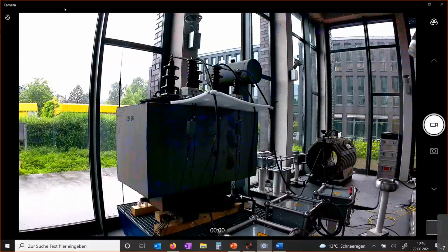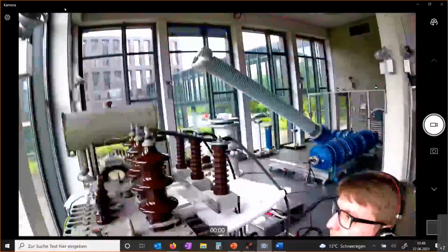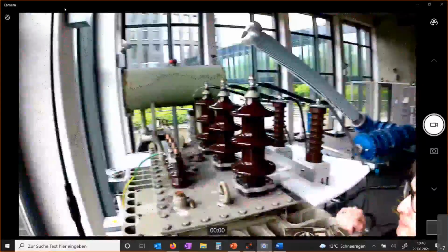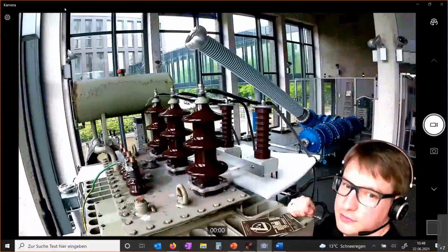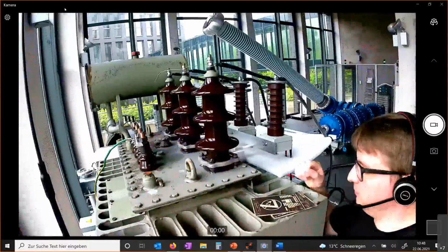Also, my colleague showed you how useful the spectrum analysis is. This is something mostly not available in most equipment. So this is an additional option in the equipment shown here, where with a spectrum option, you can see at which frequency range the signal is better and the noise is less, and you can use that center frequency. So you can select your center frequency and the bandwidth accordingly.